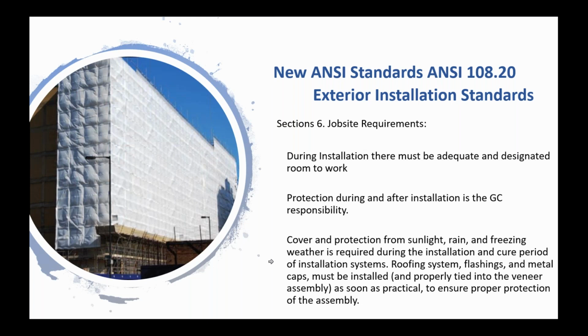Cover and protection from sunlight, rain, freezing weather in general. During the installation and curing period, roof systems, flashings, and metal caps must be installed and properly tied into the veneer assembly as soon as practical to ensure proper protection of the assembly. This is a problem we're seeing a lot in tile today, especially exterior. You're asked to go out and do the exterior of a fast food restaurant. I see it a lot there. Or it could be a large building like we see in this picture.